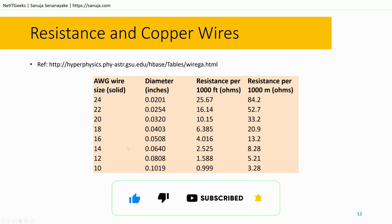You can also see that as the diameter of the wire increases, in other words, the gauge goes down, the resistance also decreases significantly. Look at the 24 gauge wire, which is 25.67 ohms, and it drops to just 0.999 by going to American gauge 10, which has a much bigger diameter than the 24 gauge.